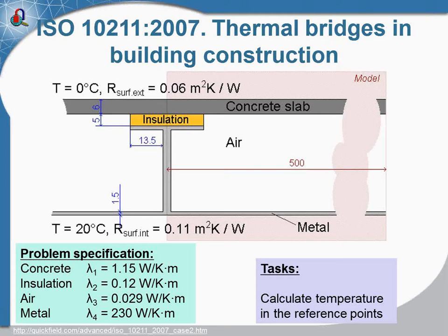Now, as this is not the solid to solid contact, but this is the solid to the gas contact, there is specific thermal conducting resistance. So this is the value of the thermal conducting resistance. The dimensions specified here are in millimeters.